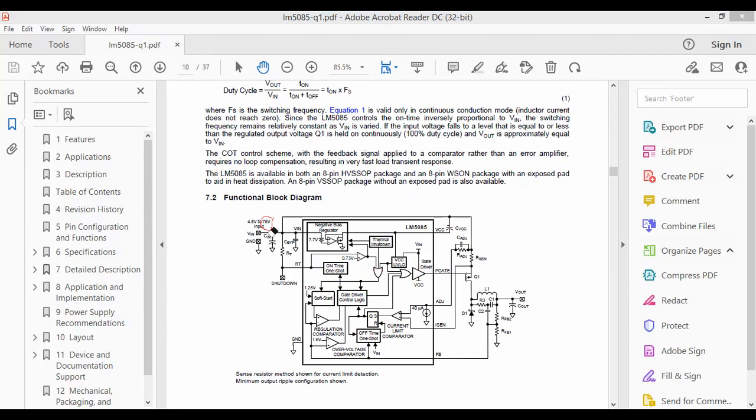So you can't directly take this pin and connect all these op amps and everything to 75 volts, because if you provide 75 volts to a logic gate, it will be destroyed, because these devices are rated to operate with a logic voltage of around 5 volts.